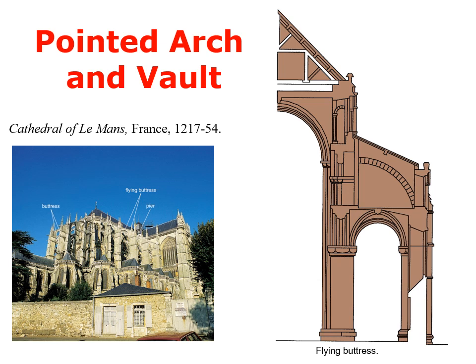So what the architects basically came up with is a flying buttress, so that you move the buttressing away from the wall itself, and that of course creates what's called a pier. From the pier are arms that come out and hold up the wall. It's basically as if you were to stand away from a wall at about arm's length and use your arm to help support the wall. That's what flying buttresses are. Buttressing would just be if you were to stand flat up against the wall and help support it.